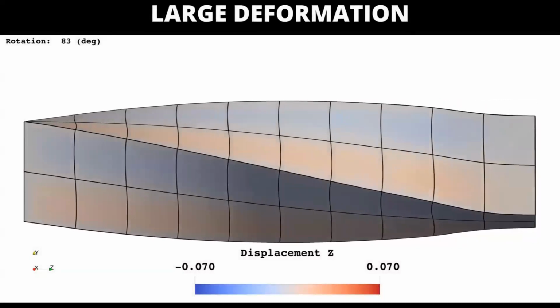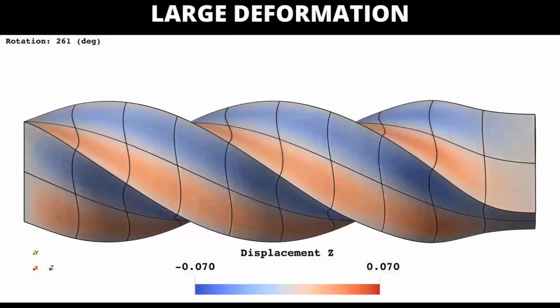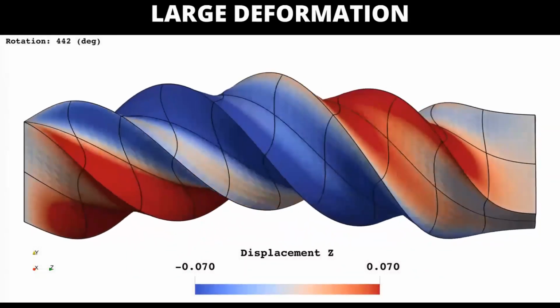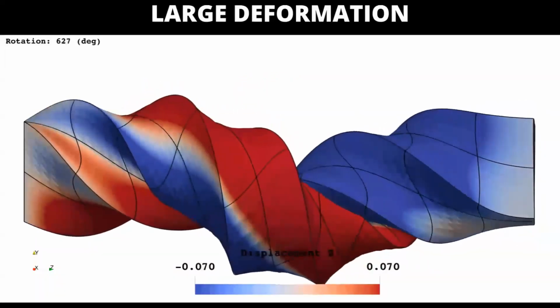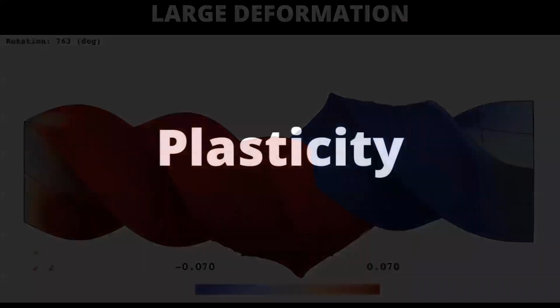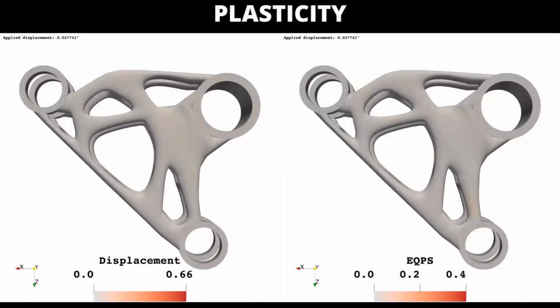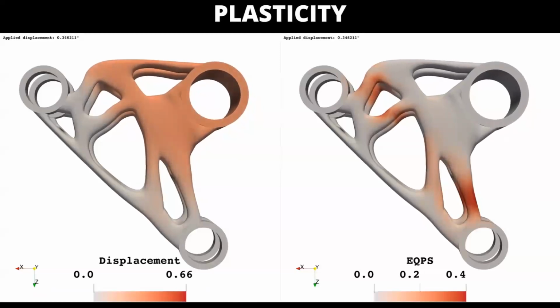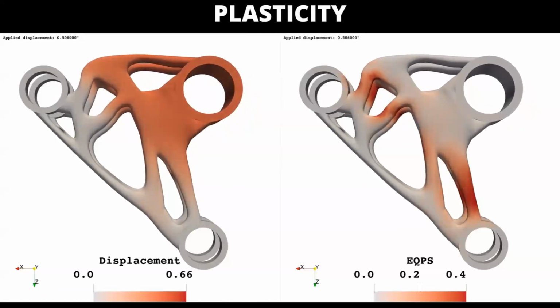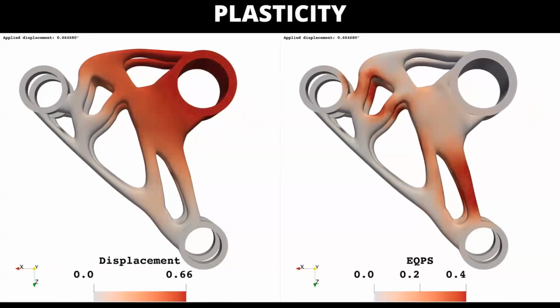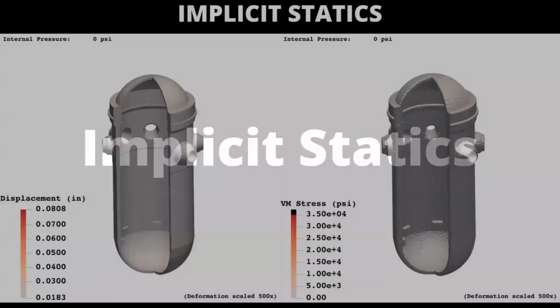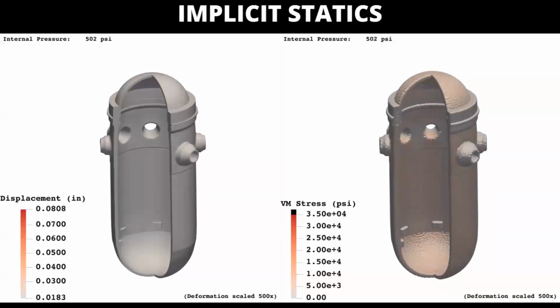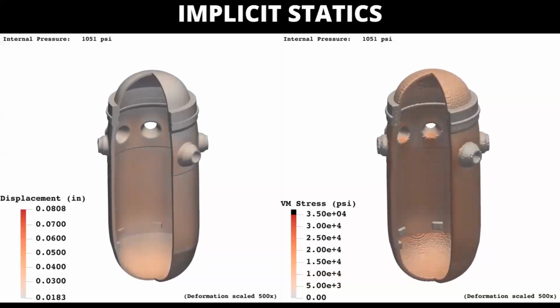Coreform IGA is, as Matt mentioned, the native implementation at Coreform that we're developing that implements the Flex IGA method. And so we can support these large or excessively large deformations with a few high order elements. We support isotropic plasticity in our current implementation. It's a material model that we have. But as you'll see later, we can really implement any material model that you would use in a traditional finite element code. We have an implicit statics solver in our code.